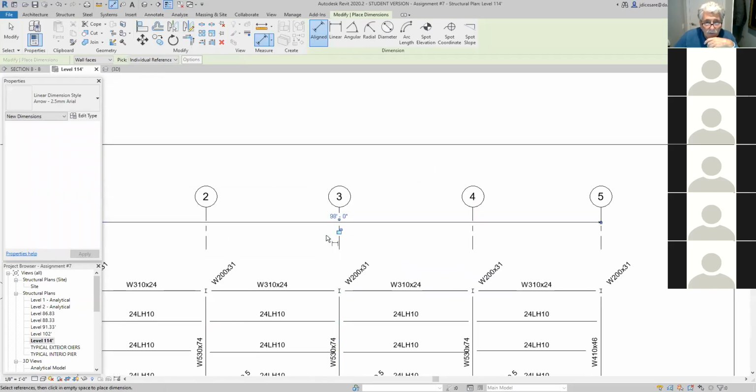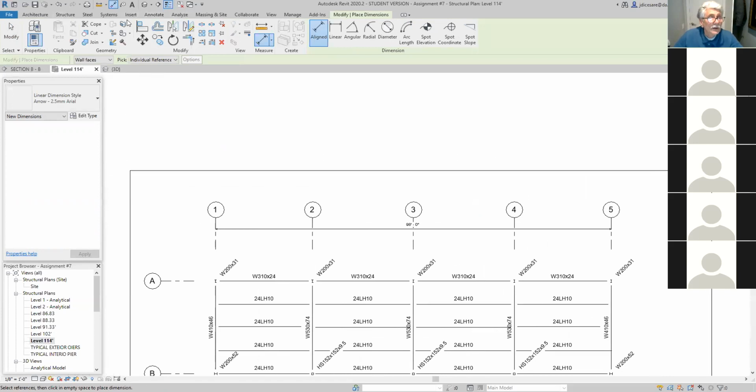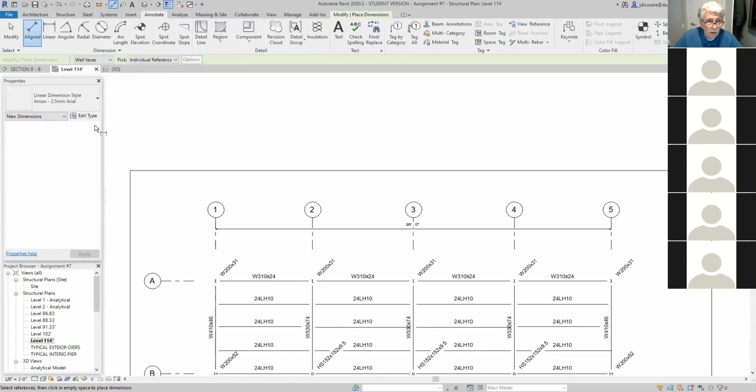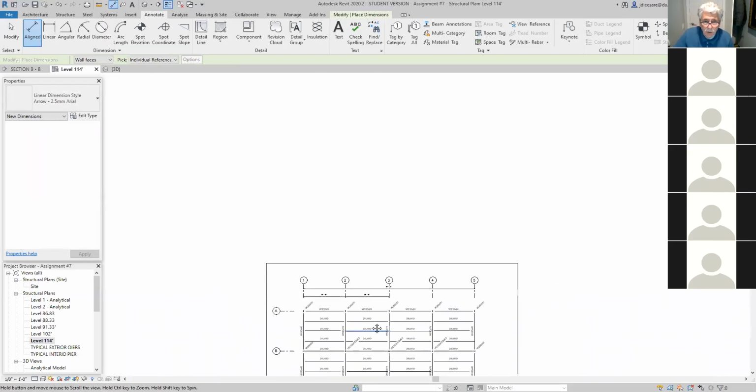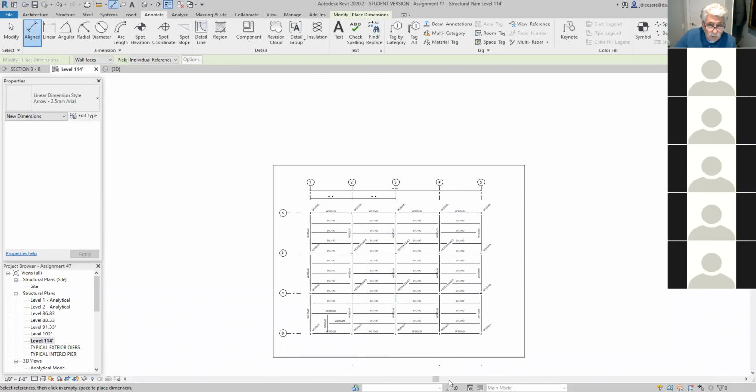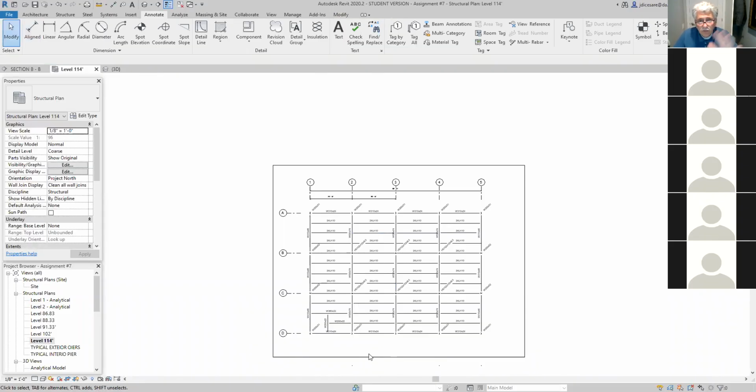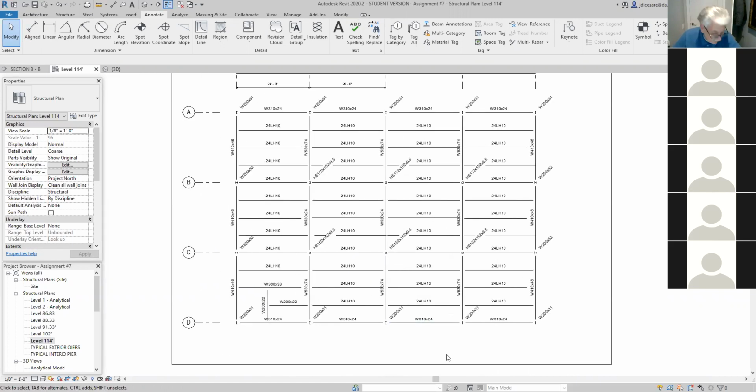And like I said, what I like about Revit, it trims a line so it doesn't intersect with the text. And then after that, you do the same thing. You go annotate, from there to there, and of course, from there to there. And then you dimension everything, clean it up. Once you've cleaned it all up, that's pretty much it. The only thing you have left to do is down here, you can put in that top of steel. In other words, you're going to go to text, put some text in there.